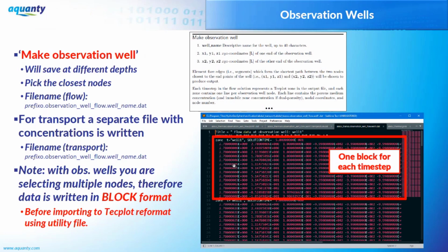If I can just chime in quickly, I would say probably the simplest way to get around this problem would be to simply assign multiple observation points instead of assigning an observation well that spans across 5 or 10 different nodes. If you're interested in a particular node and you're not exactly sure where that node lies within the range of where your well screen lies, you can assign an observation well.